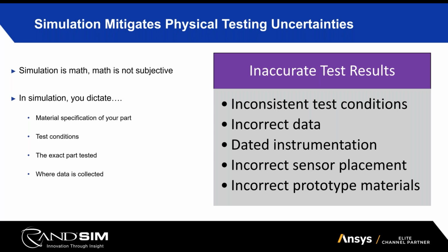A lot of these, did your supplier create the right prototype? When you're asking your supplier, hey, I want 5 copies of this version of the product for testing, are those tolerances matching up with the print that you requested them to manufacture? In terms of fit and finish, in a lot of cases, sometimes prototype materials aren't done to the same spec as production. Same thing with prototype tooling. Maybe that tolerance isn't as tight as what you would truly expect.